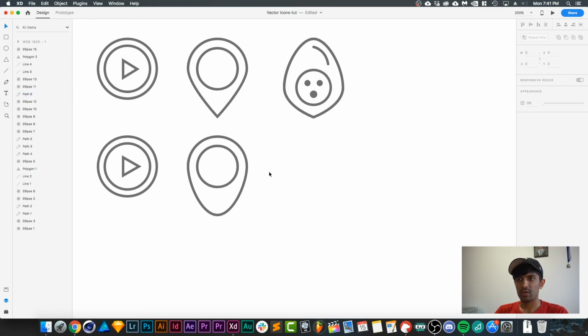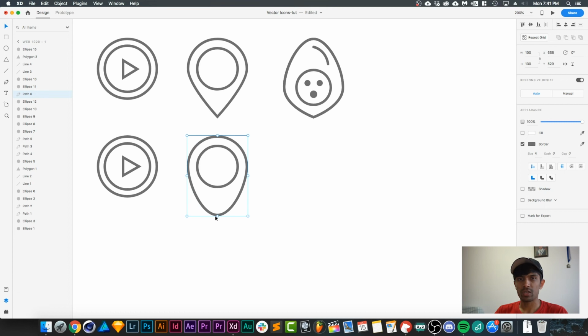And then you can either leave it like this and have this rounded like this, or you can make the end portion pointy like this. What we want to do is just double click on this anchor point, and there we go. That's how quick it was. All we had to do was just double click on this bottom anchor point, and it just automatically brought those 2 points together and made it into a point.